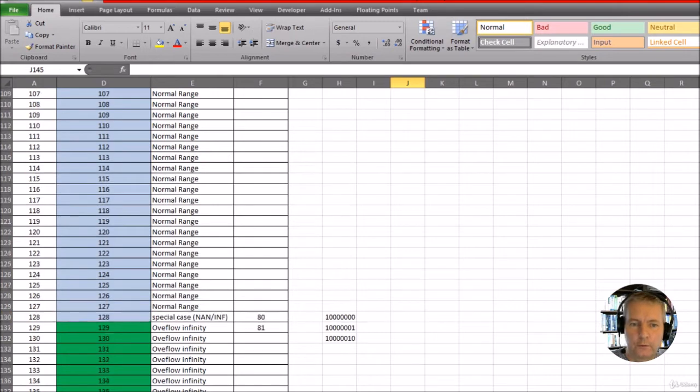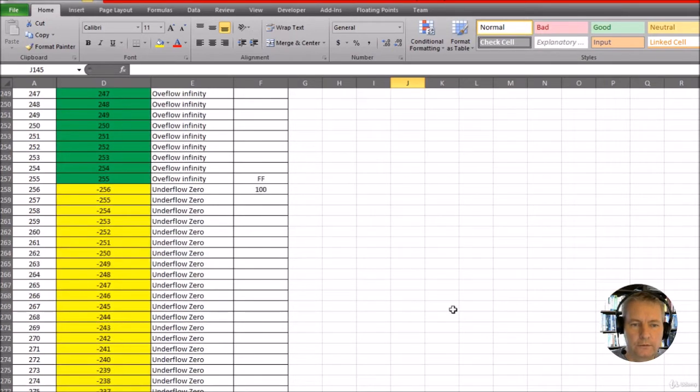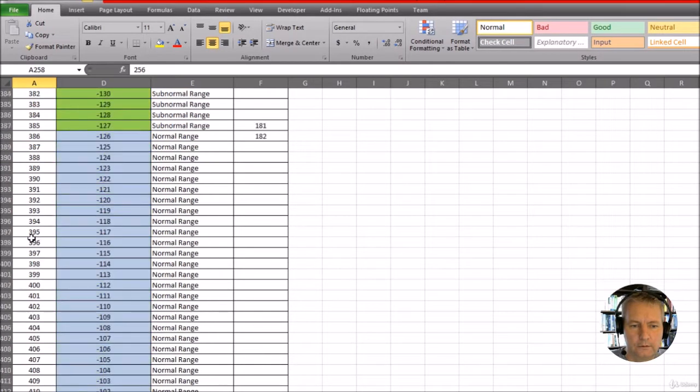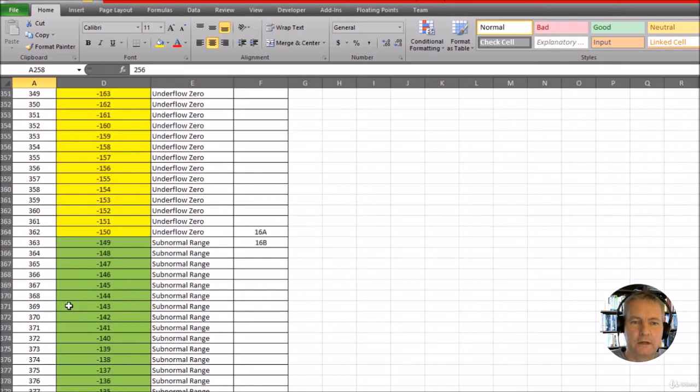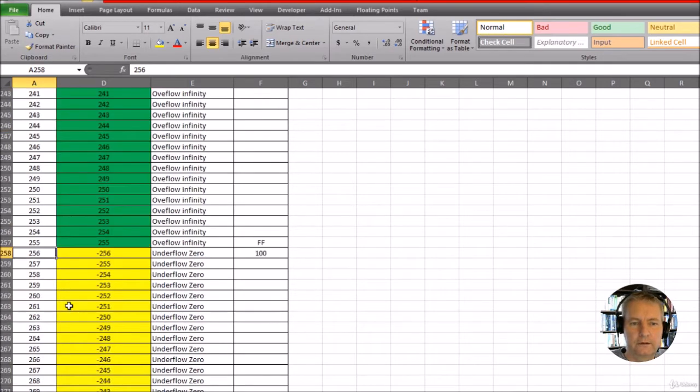So let's say we've got two negative numbers. So the negative numbers start up at 256 and they go all the way up to our value here of 511. So that means that if we were to add the two negative numbers together, then we could potentially get a number which will overflow outside the maximum range of our adder. So our adder is up to 511, and this could overflow up into a 10th bit, which we don't have instead of the 9th bit. We would just have an overflow flag come up in the adder.